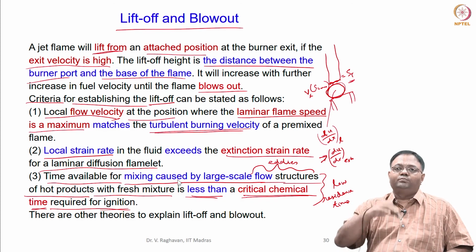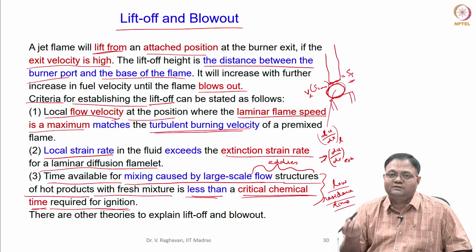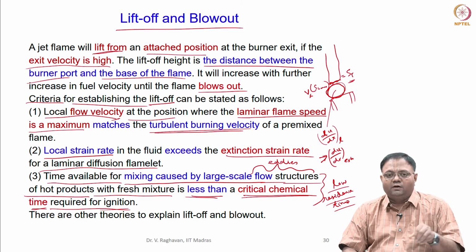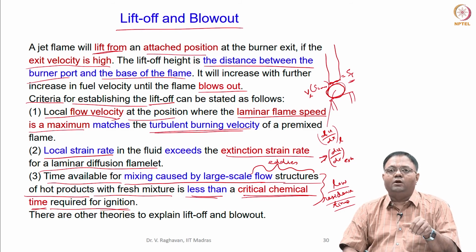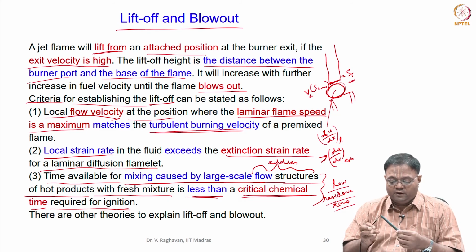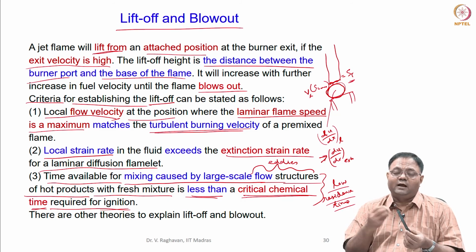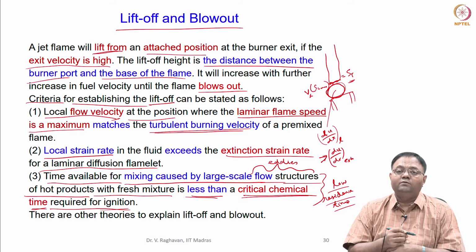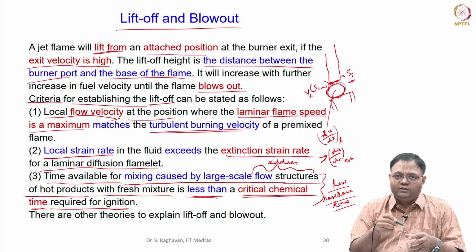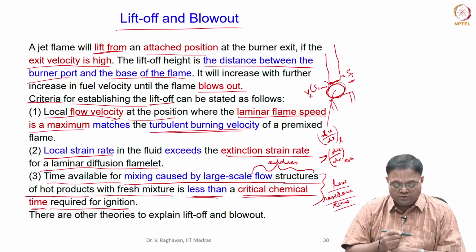So it is not able to mix properly. I will say low residence time for this, correct. The mixing cannot be complete within that particular time where the chemical reaction rate is required. That chemical time is actually more than the mixing time. So the products have not mixed properly with the fresh mixture to cause auto ignition there.